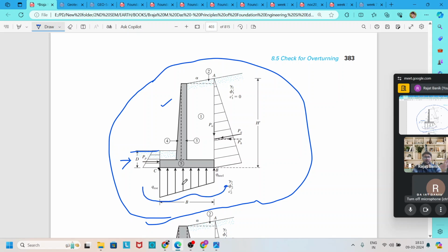If there is an asymmetry of the bearing pressure, there may be a maximum and a minimum bearing pressure. Due to this, a tension zone is created if it goes below zero, or a negative stress is created, which is very dangerous and can fail the soil by bearing.